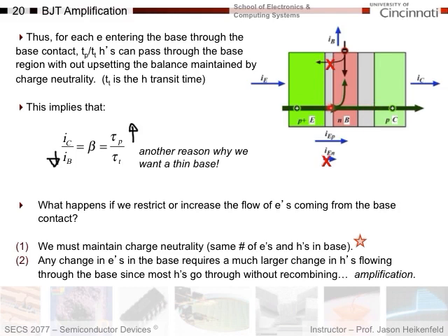Okay? They're flying through there. If I double the number of electrons in the base to 20, then at any given time, I have 20 moving across there. A great way to understand this is to consider that the BJT is just a highway and these are cars. So if I add one electron, then I could have one car, bear with me on my drawing here, moving down through the freeway, on average.